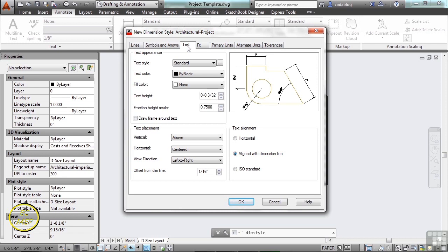Now, you can also find out that, hey, you know what, I need to tweak this drawing just a little bit, and that's okay to do. I suggest if you want to tweak a customized style, then you copy it, give it a name, and say, hey, it's based on this default style, but it's just a little bit different. Maybe it's normal-bold or normal-italicized or something else. That will help you know that you've tweaked it, it's special, and that it's okay to copy and paste it around. It's not going to override any other dimension styles at all.